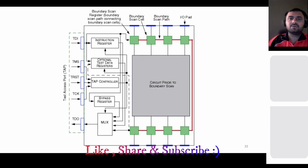So this is how it works. Here you have circuits prior to the boundary scan, then you have a boundary scan cell, and this is your IO pads, as I told, analog or digital pad. You have the pad, and then boundary scan, and then you have your circuits, and then you have this TAP mechanism or IJTAG mechanism to get this circuit tested.